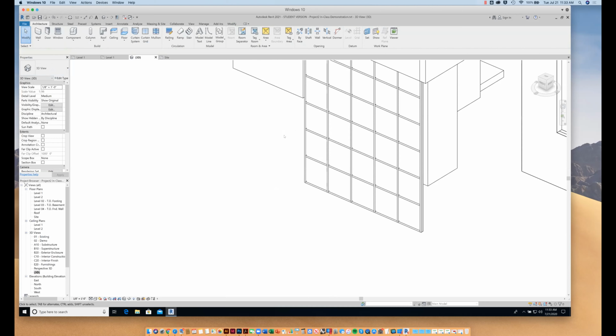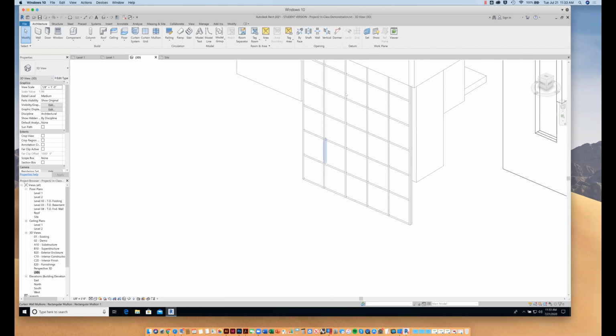So when it comes to adding these componentry and breaking down a small surface, or let's say a large surface, into a bunch of architectural components, you know, the structure holding up and the panes and the windows and that sort of stuff, Revit is much better at that than it is at modeling the non-standard geometries. So in this case, what we're doing is we're modeling the non-standard geometries in Rhino, then we're bringing them into Revit, and then we're applying the building systems to them, okay?